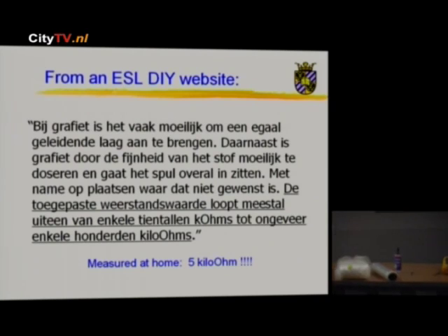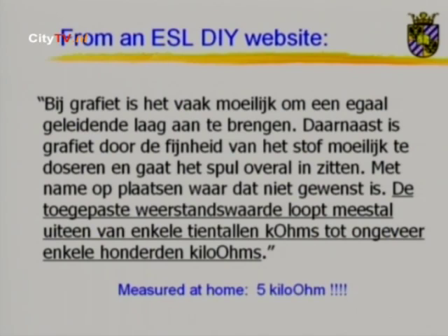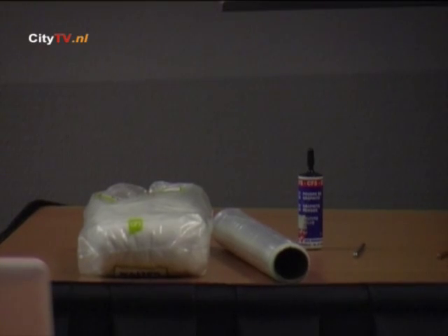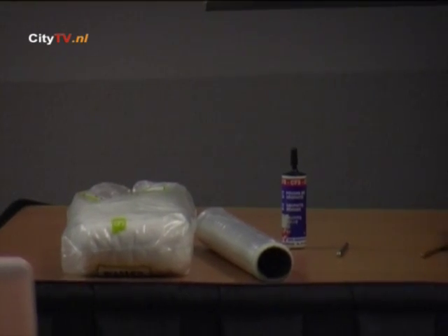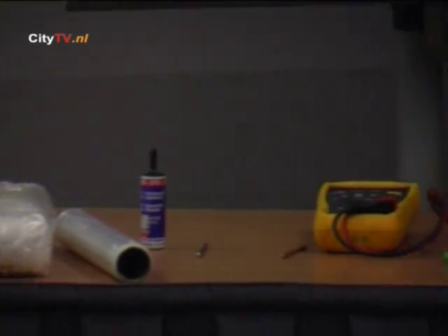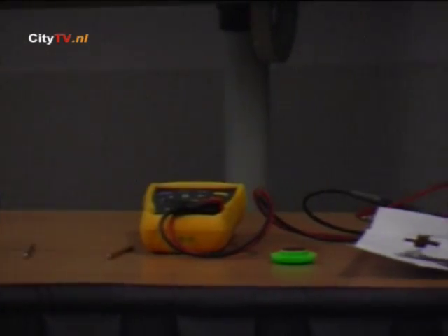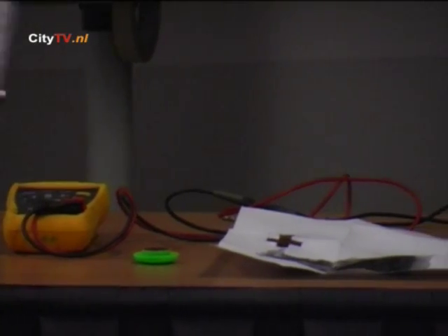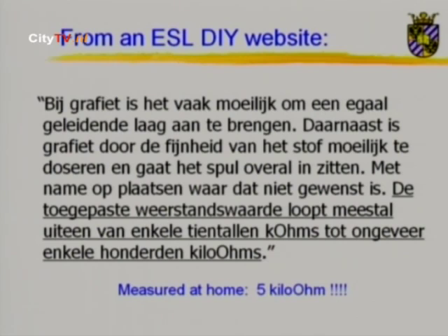And now it says, this is from a book. Well, it's in Dutch, but I will translate it. From a do-it-yourself electrostatic loudspeaker book. It says what you should do is rub out this graphite, and the typical resistance value should be of the order of 10 kilo ohm. I had not seen this, by the way, because then it would already have rung a bell, because you remember this is 10 kilo ohm, that is almost close to this unit of resistance, of conductance.